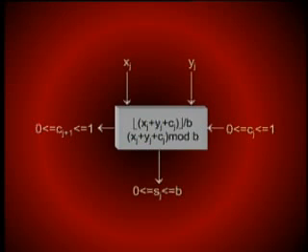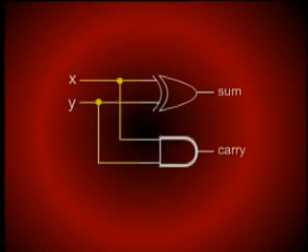Now let us look at the equivalent representation for binary numbers. For the binary number, if you look at only one stage, or we could say 1 bit ALU giving us the process of addition, and if we had a half adder, it is indicated in the slide, and you see we need just one exclusive OR to give us a sum and an AND gate to give us a carry. In this case, it's a half adder, no carry is coming from the previous stage. We have X and Y at the input.